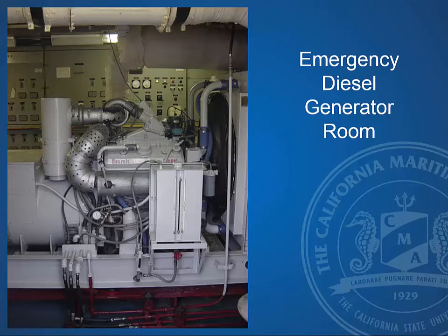Unfortunately, I've been on a vessel where I've had an engineer that shut down the emergency diesel generator by tripping that and then not resetting it. So in an actual emergency, the generator could not start because it could not inhale, could not breathe. So always make sure, because you don't want to drain your start system in an emergency.